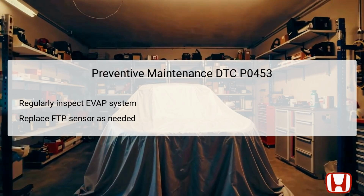Preventive maintenance is a key component to avoiding future occurrences of DTC P0453 and ensuring the longevity of the EVAP system. Regular inspections of the entire EVAP system, including hoses, connectors, and the FTP sensor itself, can help identify problems before they escalate. Keeping an eye out for signs of wear, cracks, or disconnections will mitigate the risks associated with EVAP system failures. Additionally, replacing the FTP sensor at the manufacturer's recommended intervals, or if malfunctions are detected, can prevent ongoing issues and maintain optimal performance. By implementing these preventive measures, vehicle owners can safeguard against costly repairs and ensure compliant operation of their Honda Accord.